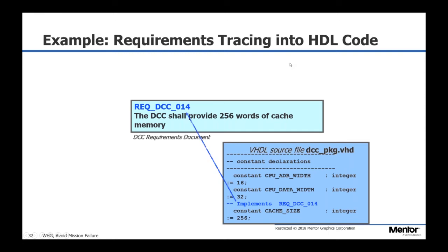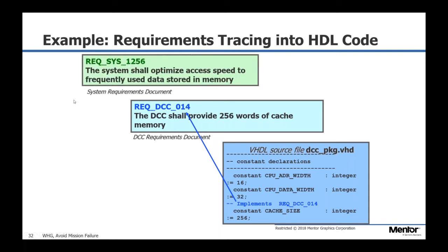Requirements tracing, as I said, becomes this process of saying, okay, I have this requirement right here, and this is where in my VHDL code I actually implemented this requirement. Putting in these implementation tags creates the linkage between the code and the design. And then here was my system requirements document with this requirement, and these coverage tags are how you specify that this design spec requirement is covering this system specification.